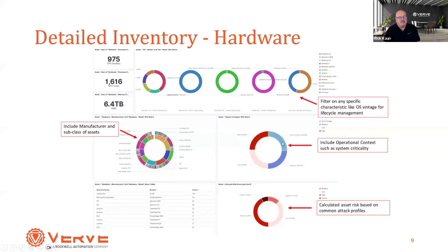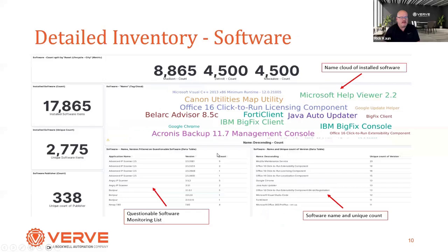Of course, outside of what's actually on the endpoint and what might be coming from the vendor, the system itself: what is its context to safe operations? Getting a handle on these sorts of things and being able to pull that in is a significant indicator of risk and helps increase or decrease your urgency. If you can eventually get to incorporating multiple of these indicators, presence of vulnerabilities, presence of whitelisting or backup status, asset criticality, vendor support for a patch, we can then start to calculate a contextual risk. And Natalie's going to go through that a lot more, so I'm not going to belabor it here.